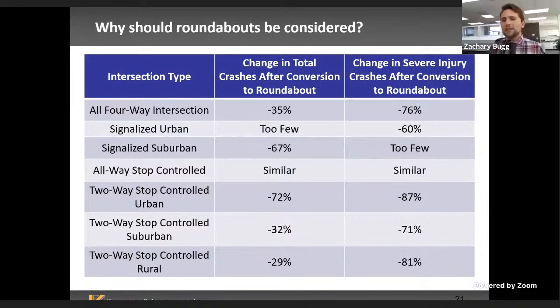So a roundabout is almost like a wide node, narrow road concept. That's what we like to say: if you have another type of intersection like a signal, you may have turn lanes that you have to develop along the length of the corridor, which ends up stretching the right-of-way impacts along the length of the upstream links. Whereas at a roundabout, you're able to use fewer lanes, but potentially have a bigger footprint right at the intersection. Good, thank you for that.